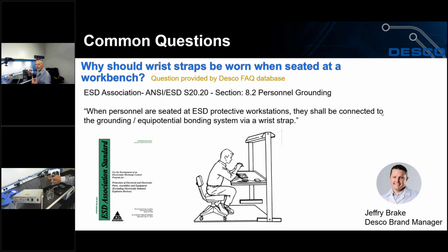So again, not only would I not be grounded per the standard, but I'm going to generate a charge if I'm not seated. So I'm going to stand up and look at the difference in the charge when I come out of that nylon material, and the thousands of volts. Okay. I'm going to sit back down, put my foot grounder back down, and now I'm grounded. So the odds of your employees having their feet on the ground all the time are not very good. So wear your wrist strap. Okay, Jeffrey? Great. Thank you, Greg.